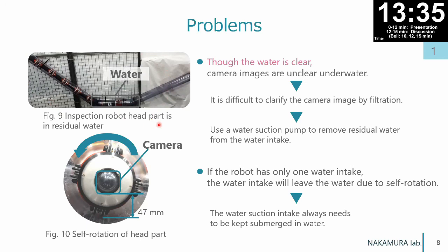So what kind of defects are you looking for? Are there cracks in the pipeline, or caving of the pipe, or is it something else? Maybe clogging the sewer, something getting stuck in there. We use this camera, and from the camera images we watch where there is a break or a crack in the pipe, and we detect it from the camera images.